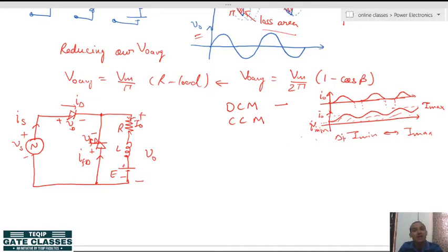Alright. And just like if you already know about DC motors, any motor, for whatever load is applied to it, will try to take a constant, continuous current from the supply, with as little ripple as possible. So, when we talk about the continuous current mode, generally for our study purposes we take its approximation as a constant current load.